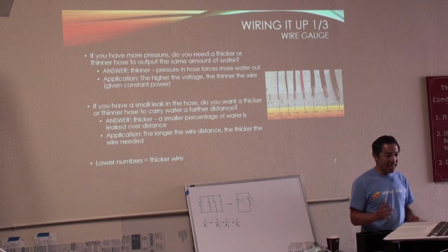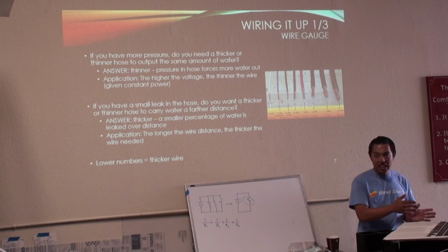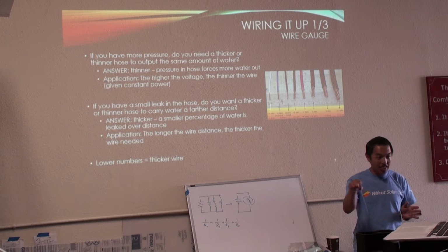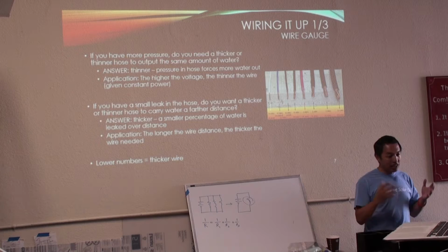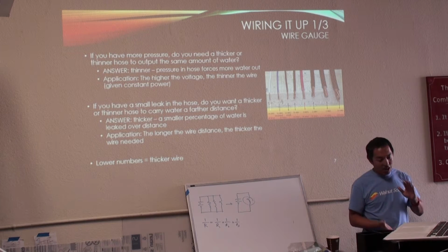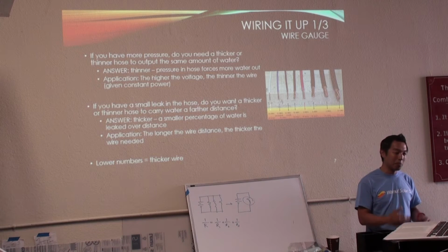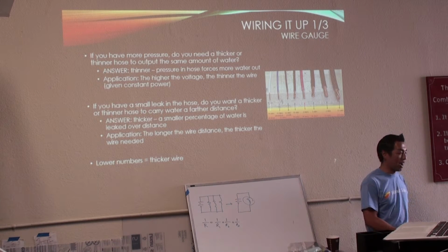If I use that for every speed, I can plot how much current the motor needs, and if we can calculate how much power we get from the solar array, we can then estimate how much discharge we're going to take from the battery.